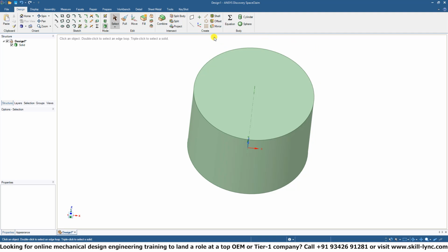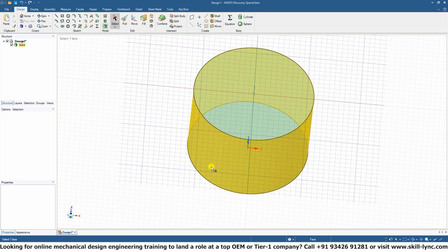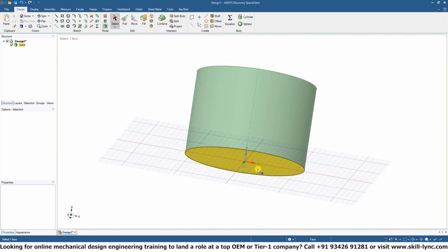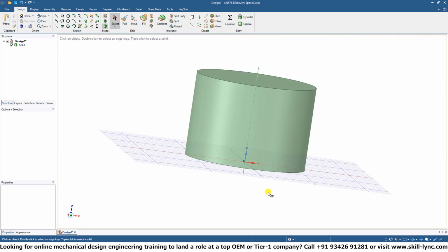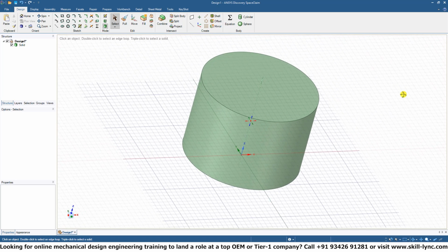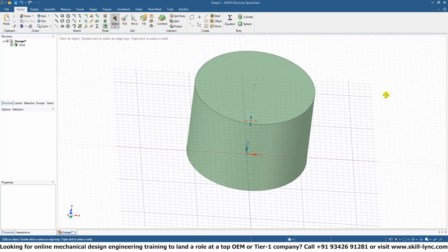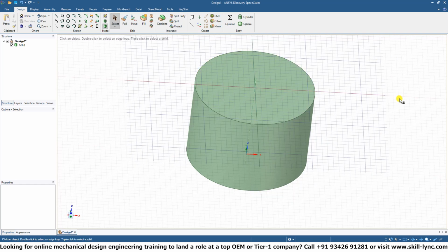How do we go about that? Well, first, you need to go back into sketch mode, because currently we are in 3D mode after the pull. Once you hit sketch mode, you can see that you are prompted to select a sketch plane. And as you highlight different areas of your model, the little helpful sketching grid also shifts depending on what you highlight. This is because right now we need to select what plane we actually wish to sketch on, right? You can't sketch in 3D space, really. You can only sketch on a plane.